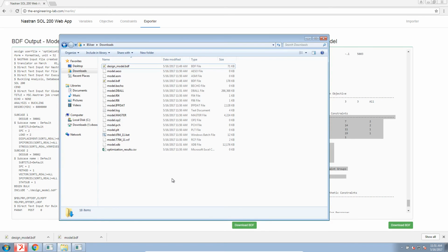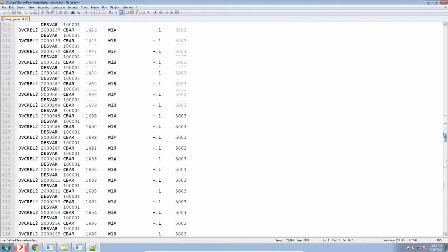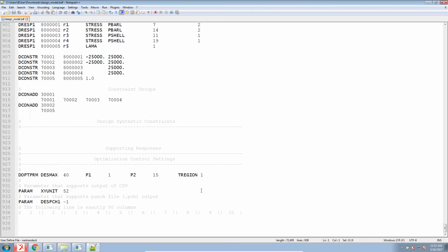So if something would take 40 design cycles before an optimized model is found, with the truss region, you could potentially minimize it to 30, 20. It's very case dependent. So in the model, I made the modification. I said, turn on truss region, set it to 1, meaning we're using the truss region. And it's going to recycle some of the approximate models during each design cycle.